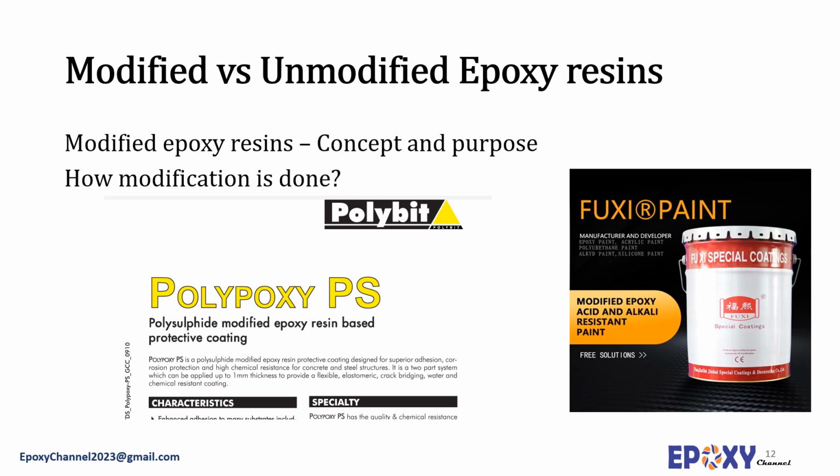The use of a diluent or reactive diluent to modify the viscosity of an epoxy is a common practice in modifying an epoxy resin's viscosity. Diluents will be presented in a separate video. Unmodified epoxy resin is often called a universal epoxy, derived from the sole reaction of epichlorohydrin and bisphenol A, and no other components or blends are added to that.